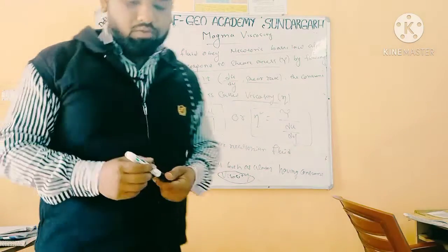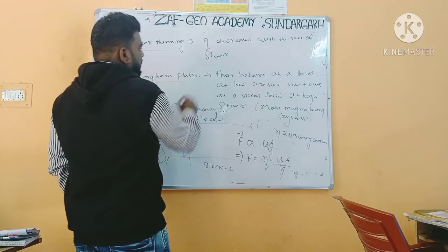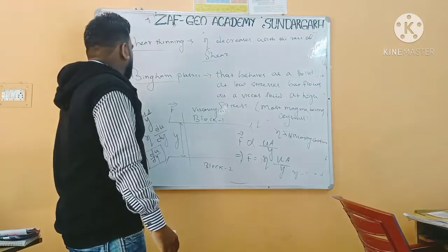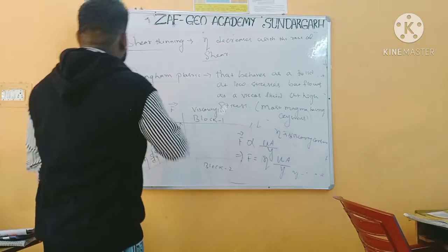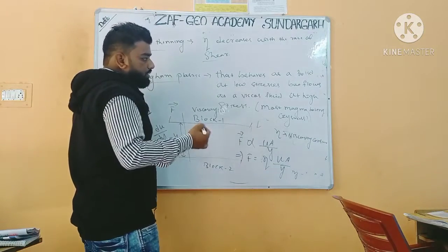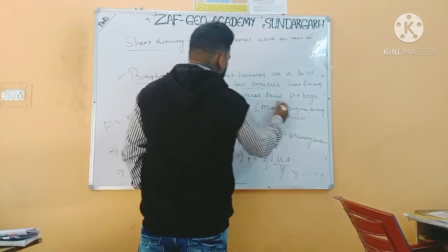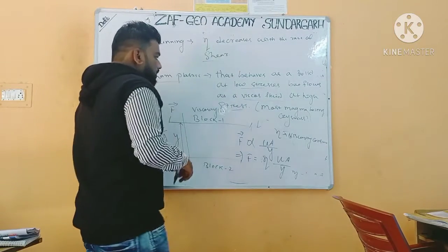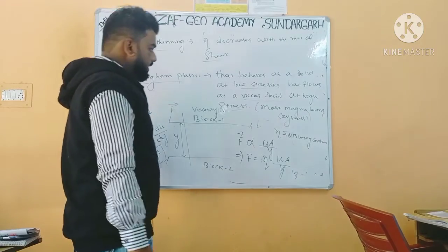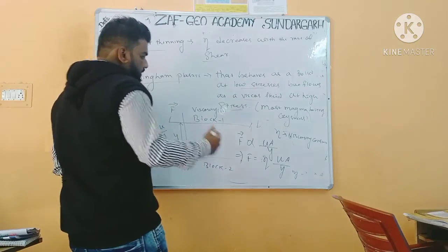Okay, shear thinning. So eta, the viscosity, decreases with the rate of shear. And now another important term is Bingham Plastic. Bingham Plastic is a material that behaves as a solid at low stresses but flows as a viscous fluid at high stresses. Okay, so a Bingham fluid behaves as a solid at low stress rate but flows as a viscous fluid at high stress rate.